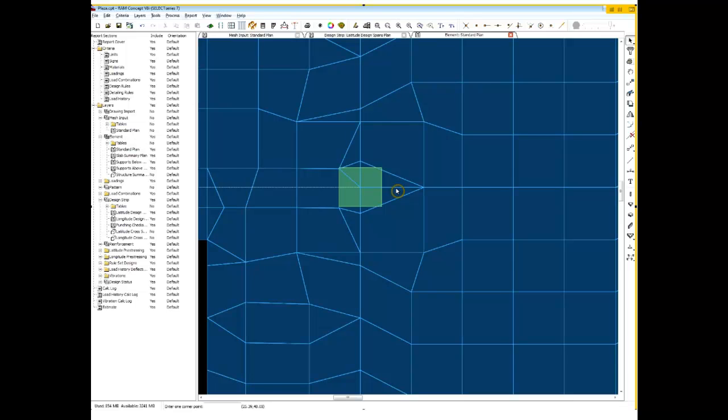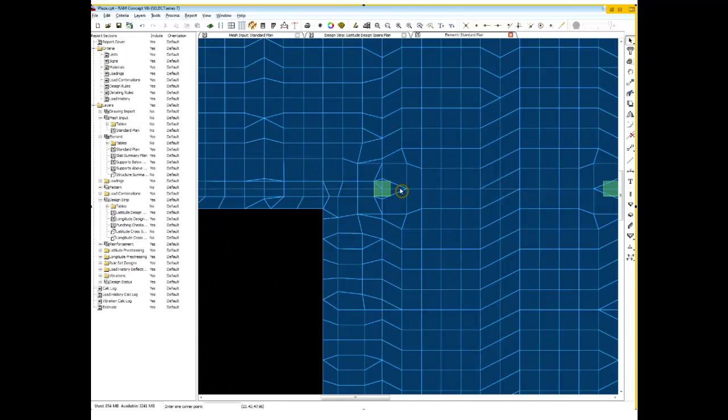What you will see though in certain situations, like 2 slabs coming together perhaps, is if it merges that node together, you might see an anomaly of difference in slab depths or difference in the slab edge that you didn't define. And so that's what you'll be able to detect on the element plan.